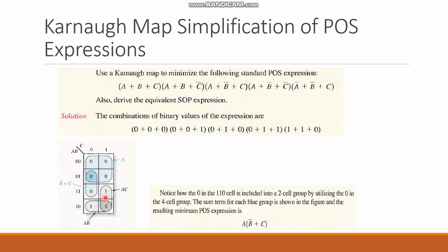However, for the sum of product, we could just refer back to the previous method, which we were talking about. Here, B has participated with B and B complement, so you remove the B. A is the only one remaining there, and C has participated with only C, so it's going to be AC. And for that group as well, we come back to the sum of product. However, for the product of sum, everything is going to be different.